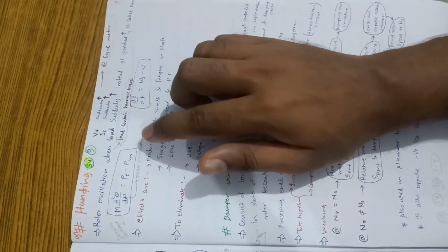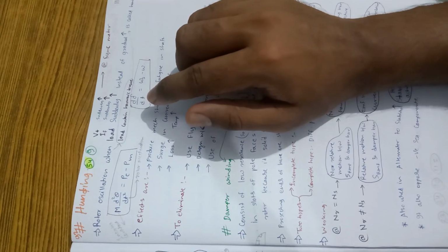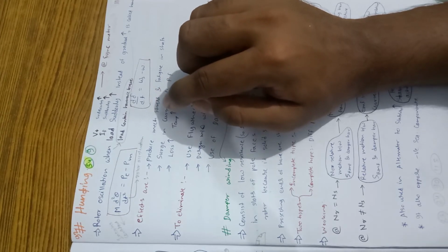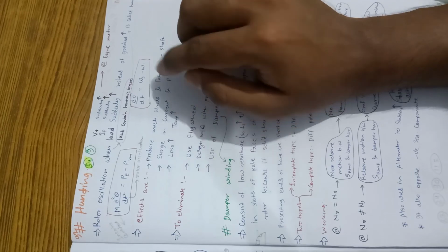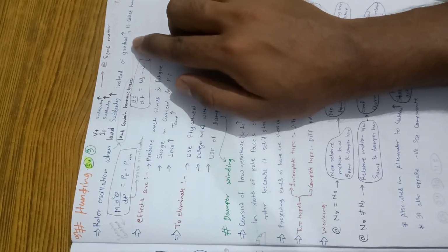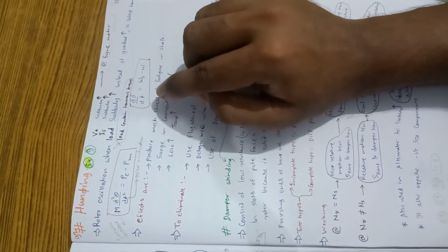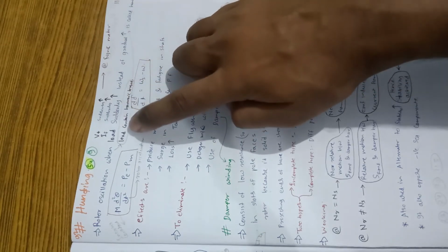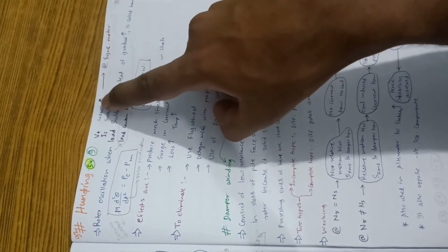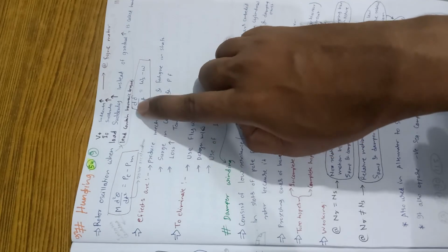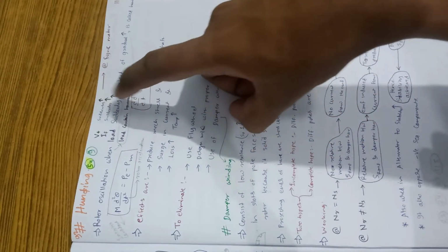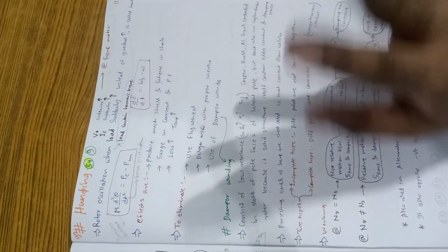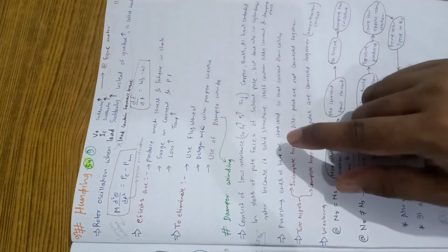Rotor oscillation that is seen when VT is suddenly increased. Okay, terminal voltage suddenly increases, or field excitation is suddenly increased, or load is suddenly increased instead of gradual increment, or load contains mechanical torque harmonics. This is called hunting. There are four reasons: VT suddenly increases, IF suddenly increases, load suddenly increases, load contains harmonics. Due to any of these reasons, if there is oscillation in the rotor, then we say it is hunting. That is only the meaning of hunting in a synchronous motor.